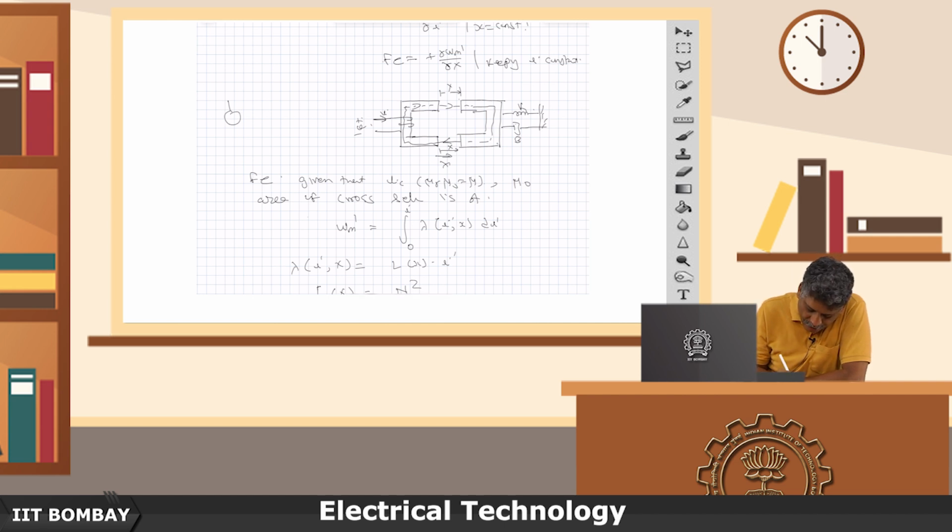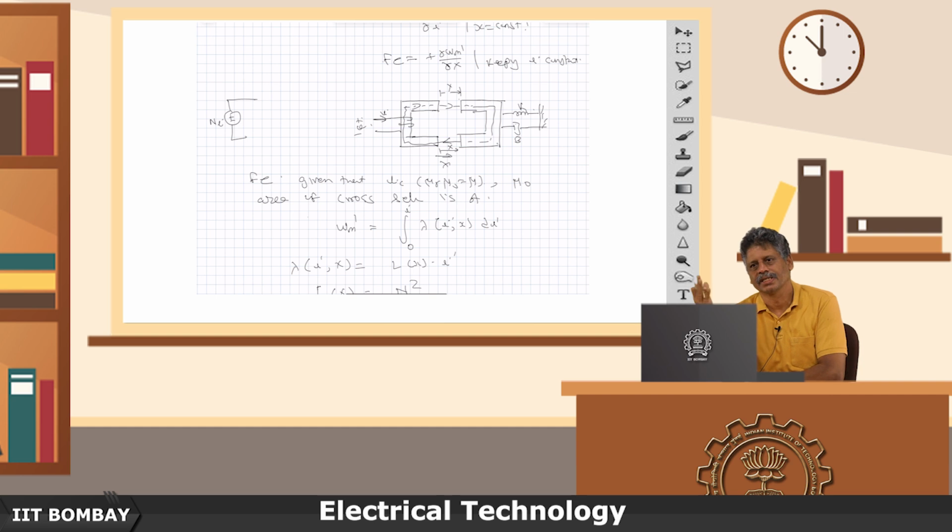If you want to calculate the reluctance, you can write the equivalent magnetic circuit. The equivalent magnetic circuit is going to be this, which pushes N i, and this part of core and this part of core, all having area of cross section A. Anyway, fringing and leakage flux has been ignored.